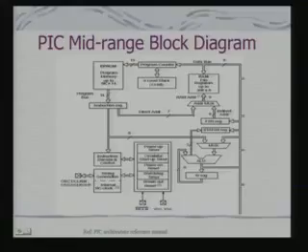So when the timer finishes its count and it has not been reset, it will generate an interrupt, and that interrupt will enable the system to go back to one of the known predefined states. Okay. So this watchdog timer is a very important component.